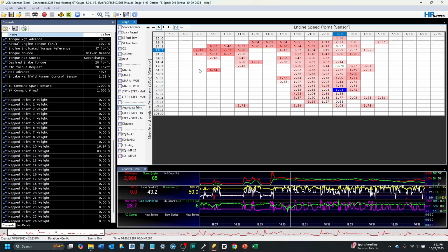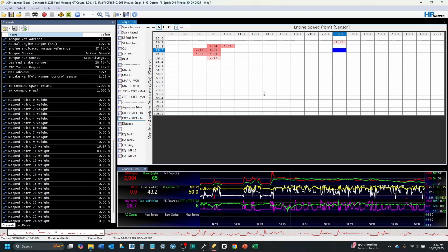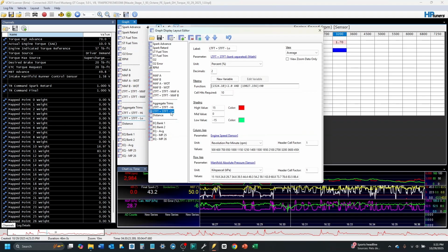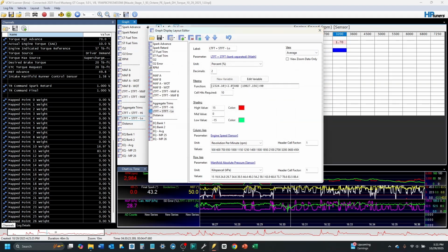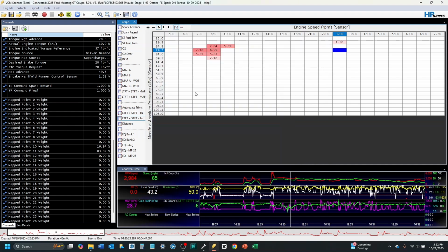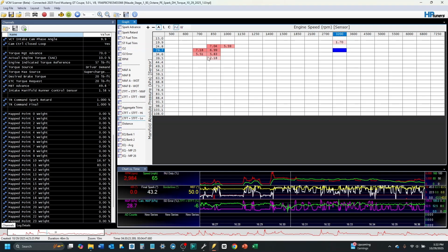And so when we want to actually zero in on a few things, I can go to, remember these histograms I created? Very interesting. So looking into this again, for low, I'm looking at map point 10. Just map point 10. Show me just those things where the IMRC is under 2 volts, right? If I filter on that, give me the low state and map point 10, here we go. Those are lean. So what I know I can do now is go into map point 10 and start touching those up. I'm not going to do that till the next run, but it tells me that I have work to do on map point 10.